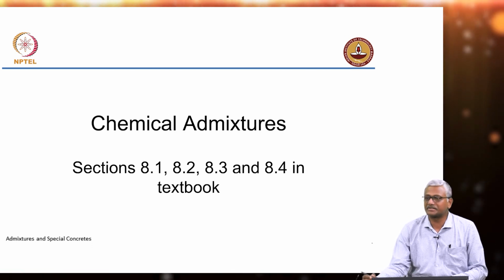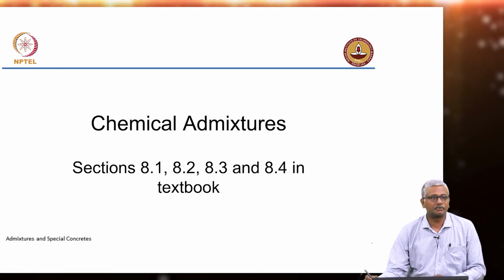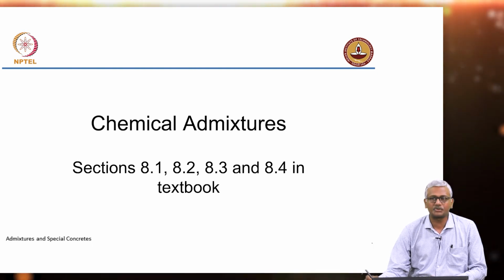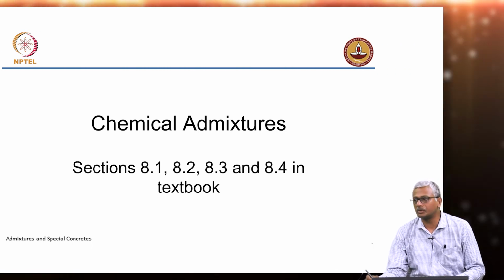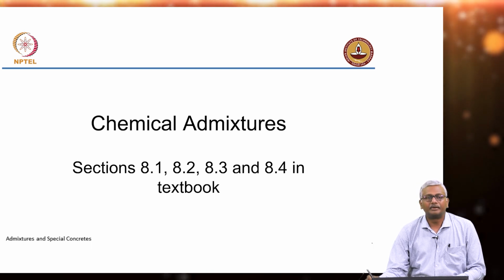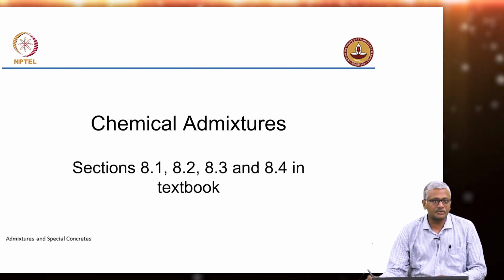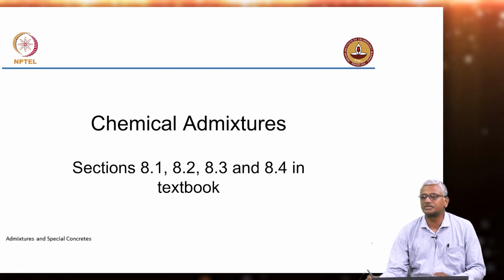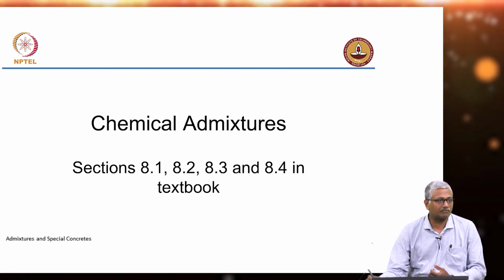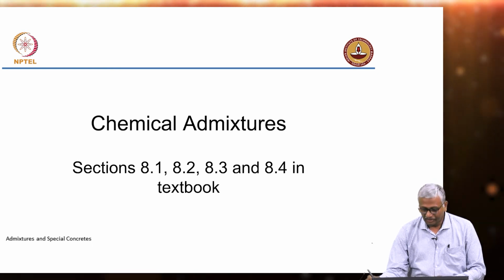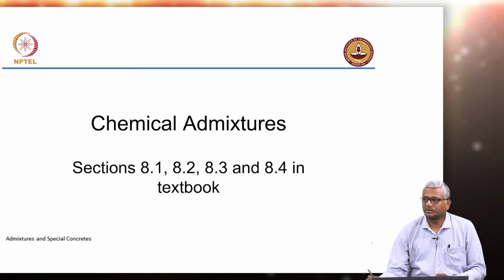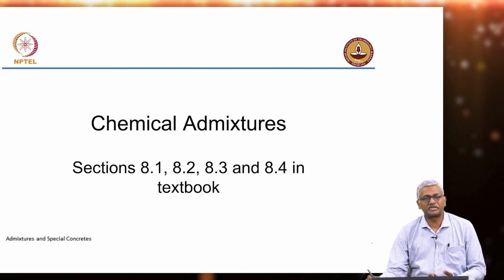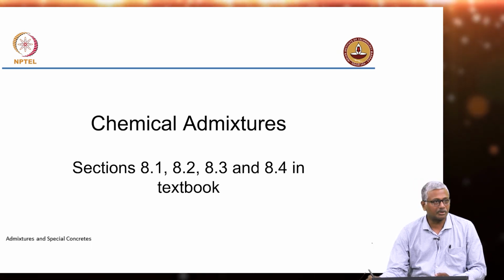We'll resume our discussion on chemical admixtures. So far we have looked at water reducing agents, then we talked about set controllers, air entrainers, right? And we also then talked about viscosity modifiers, which required some additional understanding of rheological approaches to understanding concrete fresh characteristics, okay? We'll today move on to corrosion inhibiting admixtures and other specialty admixtures that are typically used for concrete applications.